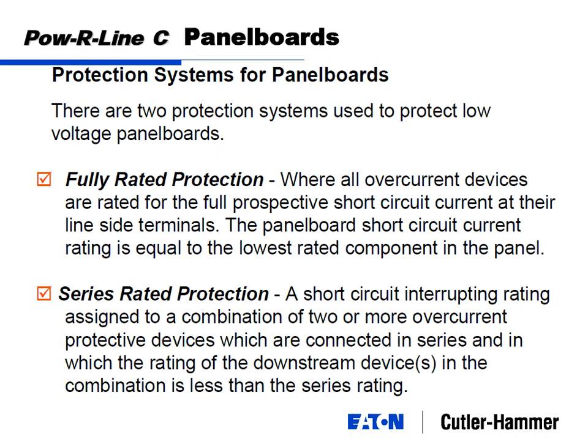And how do we do that? Basically, we take the two circuit breakers, the main and the feeder, we put them on a bench test, we inject them with the current that we want, and we say one of those two breakers will trip. We're not going to tell you, or we don't care, which one. So if one of those breakers trips, it takes your panel board offline in the event of a fault.